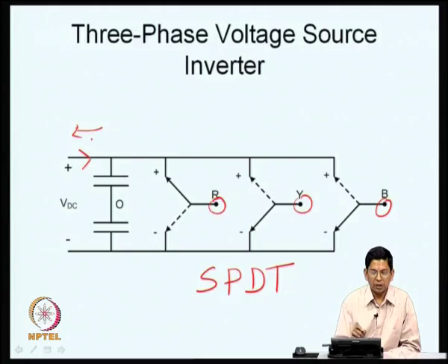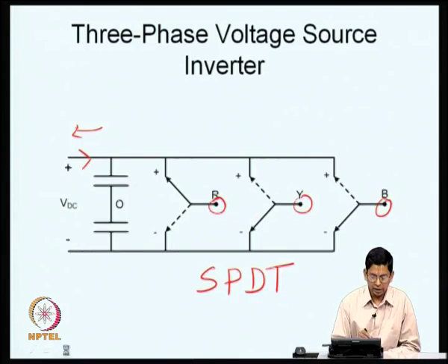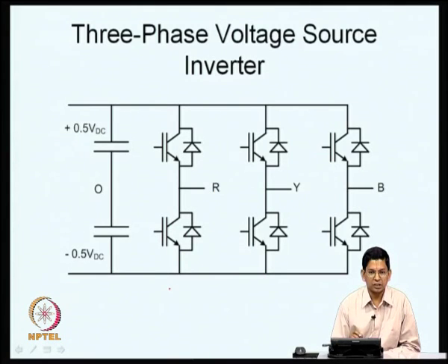If it is flowing from the AC side to the DC side, the phase angle between the voltage and current will be greater than 90 degrees, closer to 180 degrees, so to say. And so, it is really a bidirectional power flow converter, and the actual switches are realized like this now. To restate whatever I said, this is the pole of a single pole double throw switch.